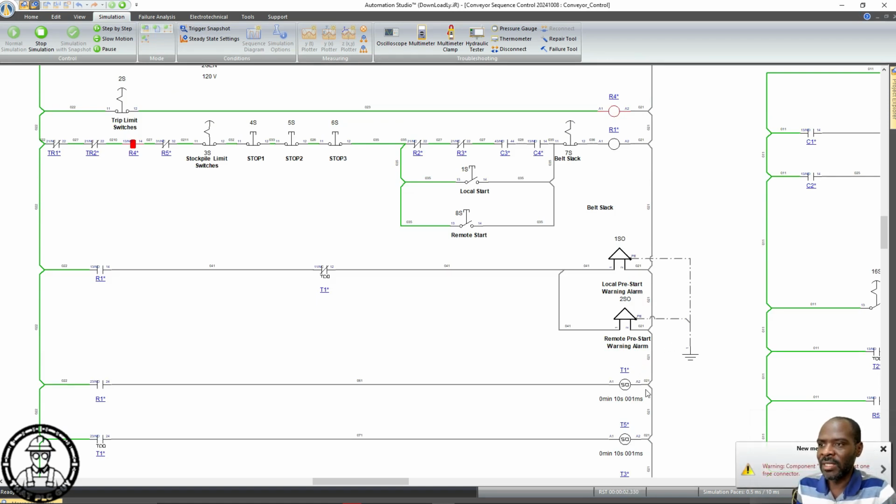We're going to time it to see how the actual time stacks up against what we set, because normally you'd find a kind of discrepancy, like you get a higher time actuation. If you set 10 seconds, you may get something in excess of 10 seconds. So we just want to know what this 10 seconds comes out to be, right? So we're just going to time this.